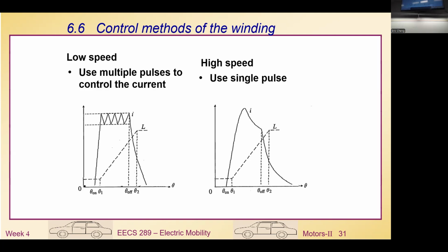Also, when the motor rotates at high speed, we do not control the profile very well. The profile increases and decreases, so this is not a constant current. That's why the torque ripple here is also not that good. So this motor supposedly has higher torque ripple. But of course, that's only in the old textbooks or old stories. Today, we are able to use really good control to control the profile, and in this case we're still able to control good torque. This technology is already readily built up by my team, so we don't worry about this kind of torque ripple issue.